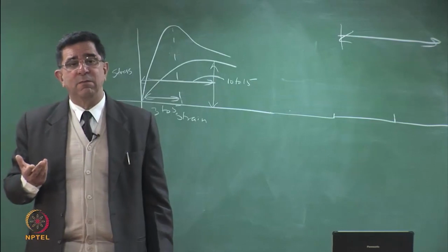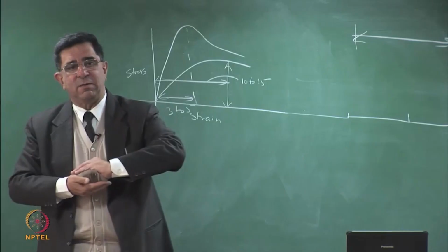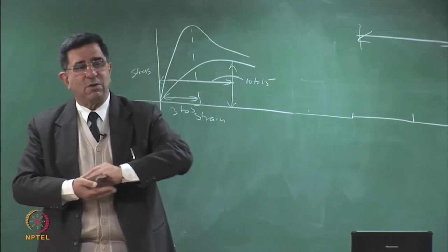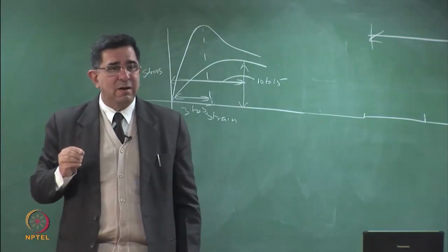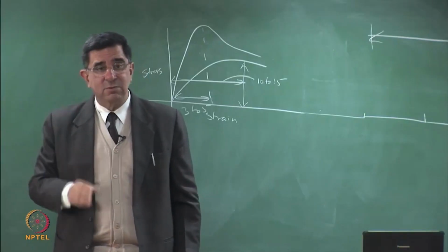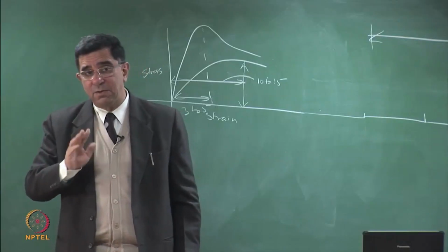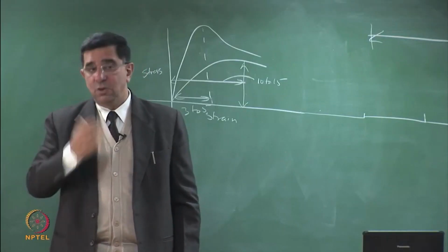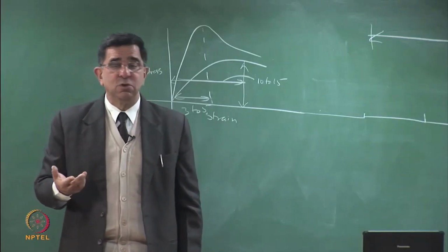How is the weld made? It is just two hot points which are running across, they seal the polymer together. So once you have found the leak, you can do a patch weld, you can put an extra patch, and heat it, and just like a puncture, this will be sealed. The only thing is locating it, for which typically a soap solution is used.